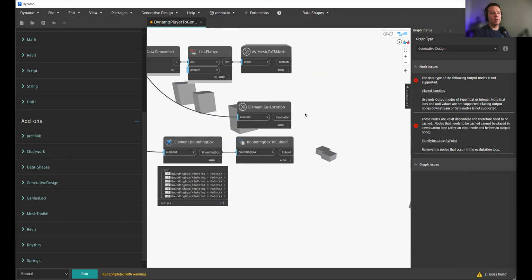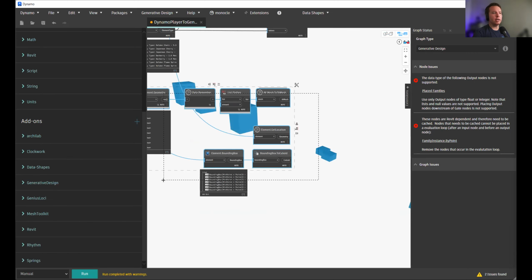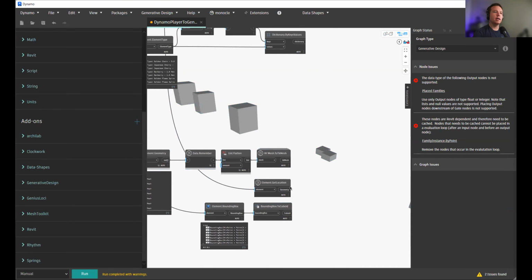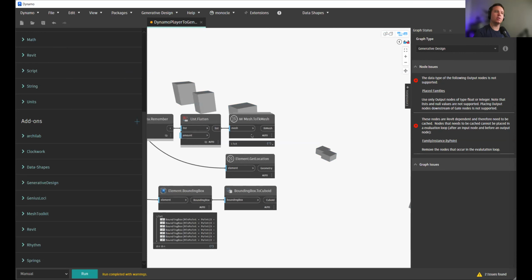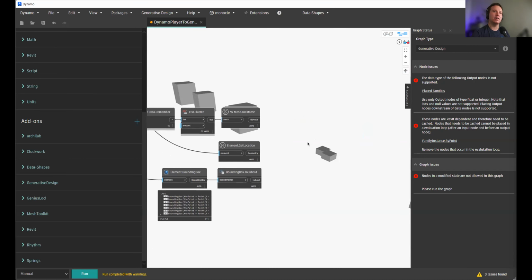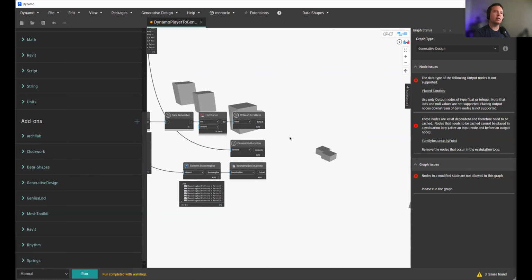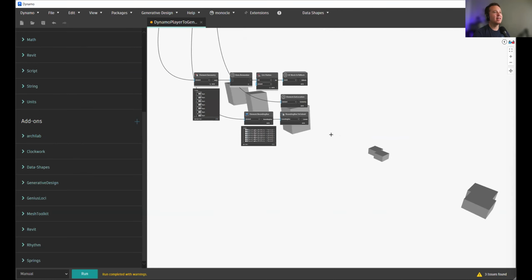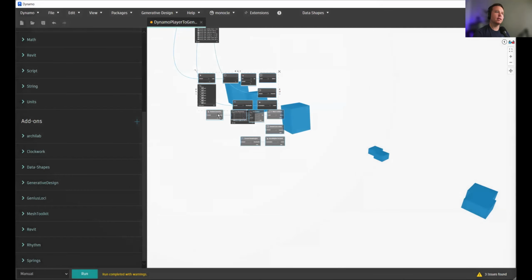So yeah, what we would do is we're actually going to build a dictionary that looks up all of this data that we worked so hard to build. Traditionally, in the past, we've done this where you reuse the node over and over. So if you find yourself down the line getting the element type, and you're like, oh, I gotta get the mesh again, you messed up. So try to use dictionaries if you can and minimize the data that you're having to push around. If you're sitting there and your Dynamo's thinking, and you see, all right, so tangent here. If I ever have to evaluate someone's graph because they're like, hey, it's going slow, can you help me? And it looks like this.